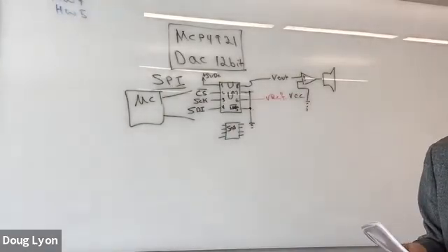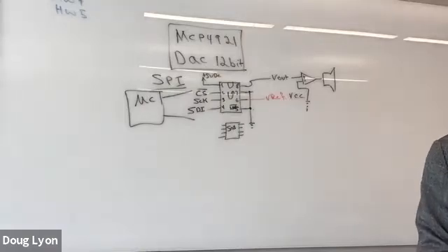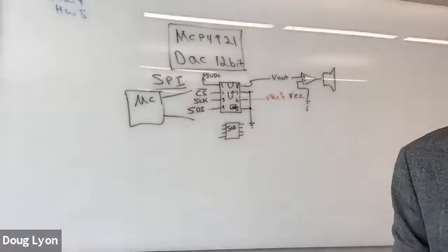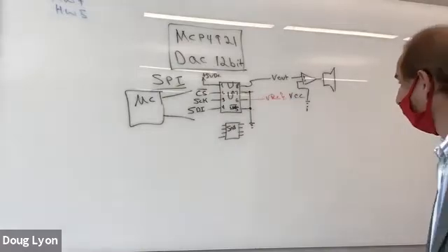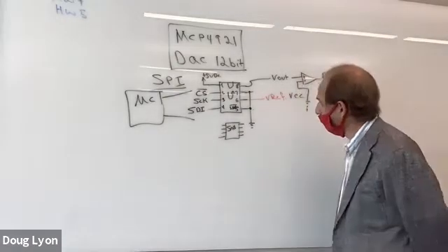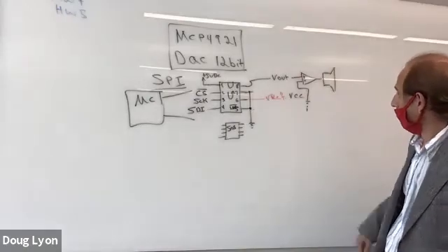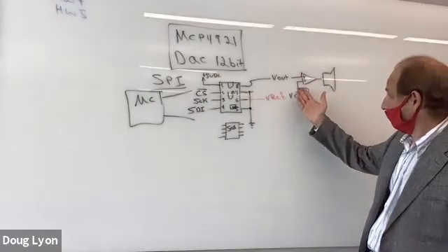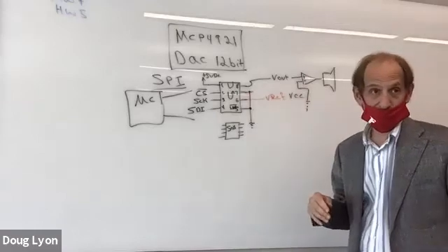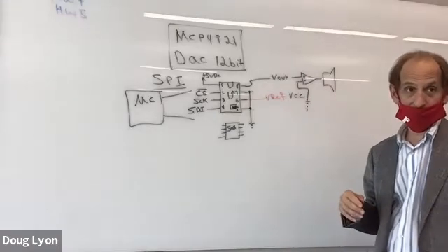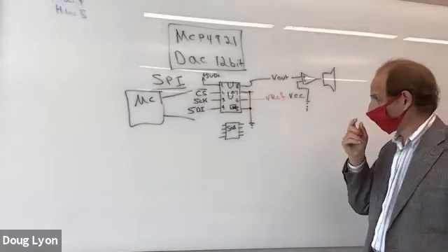And question 1 asks, can you drive a speaker directly with the DAC? And the answer is no. It cannot sink the current. You need to have an amplifier. If you were to plug your headphones, real 8-ohm headphones, directly into this DAC, it would sink way too much power, and it would blow out the DAC. So you've got to be careful.